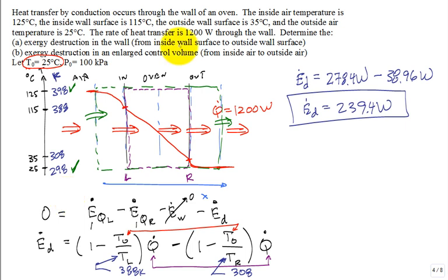So you do the same type of calculation, and you'll find the exergy destruction rate: exergy transfer in 301.5 watts minus 0 watts. Hold it. I have 1200 watts being transferred out over this right surface of this extended control system or control volume, right?